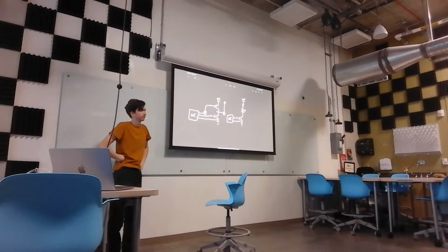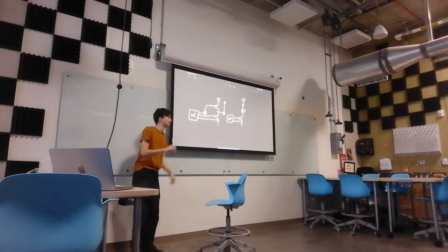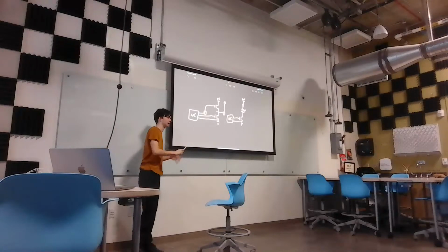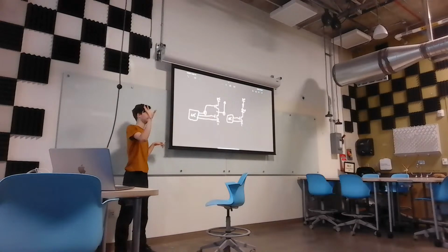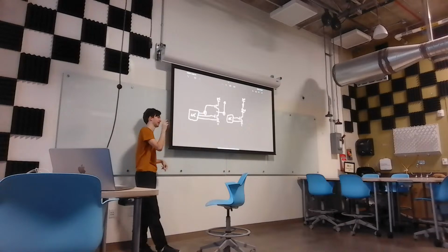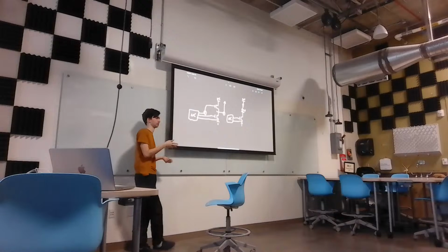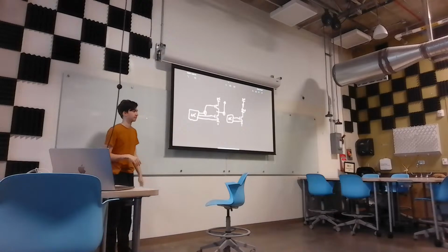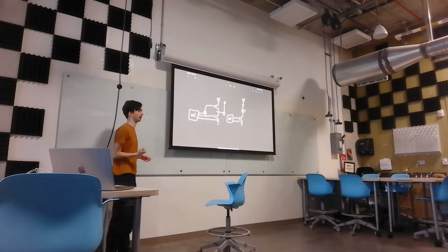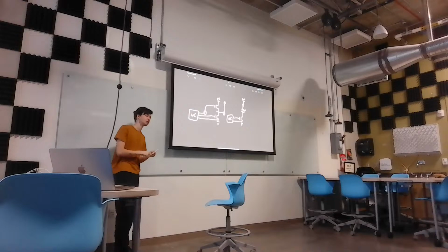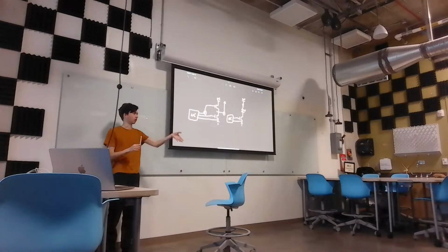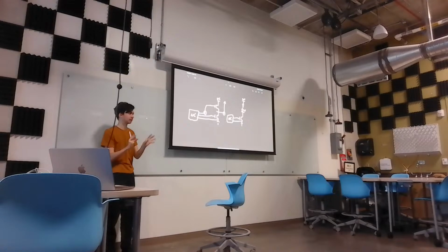So one of them is a P FET, the other is an N FET? No. If it was a P-channel MOSFET, then we could just go floating, and then the resistor pulls it up and makes that super high voltage, using a high voltage tolerant microcontroller. And then when we want to, we pull it down to ground. But P-channel MOSFETs are worse than N-channel MOSFETs. We want these MOSFETs to be exactly identical, so when we're switching on and off, it's the same figure.